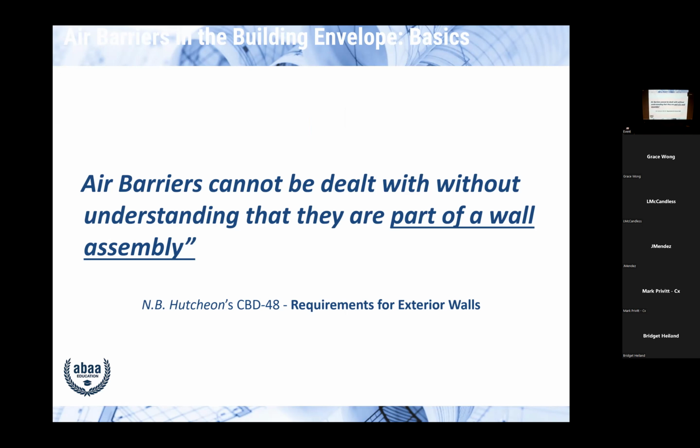So, okay, where's it coming from? Well, it's not from the outside. We can show it, we can prove it. Well, then it's got to be coming from the inside. Vapor barriers were born. So that was the mantra in those days. You have to have a vapor barrier in your building all over the place. And we still had water in the walls. So where the heck is this coming from? It's not coming through the material. We got water shedding on the outside. What's left? Well, that's when air leakage started to be a concern.